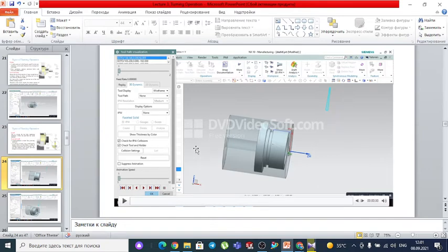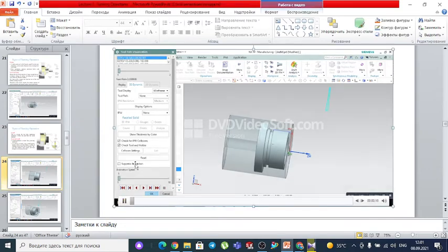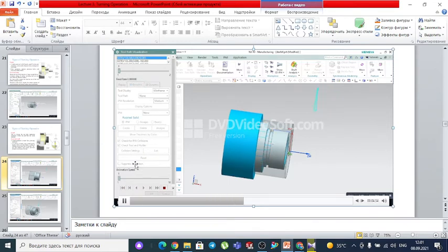So I think this is, or no, maybe let's see it. Maybe it is grooving. So this is our overstock, and it will cut it. You have to be careful while selecting the tool for the cutoff, since it should be long enough in order to cut. So it is the cut.